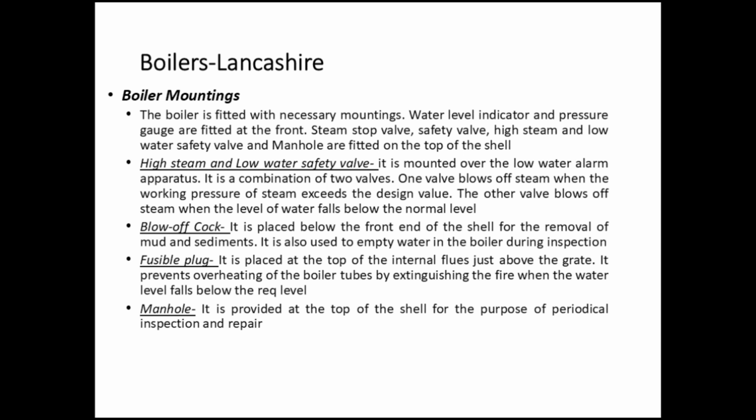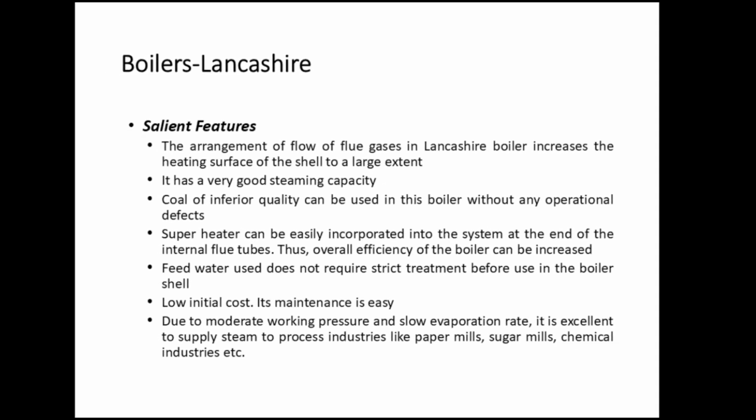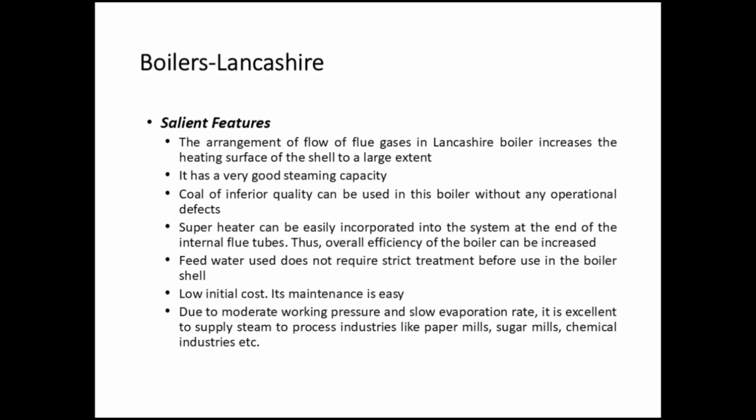Manhole. It is provided at the top of the shell for the purpose of periodical inspection and repair. Boilers, Lancashire. Salient features. The arrangement of flow of flue gases in Lancashire boiler increases the heating surface of the shell to a large extent. It has a very good steaming capacity.